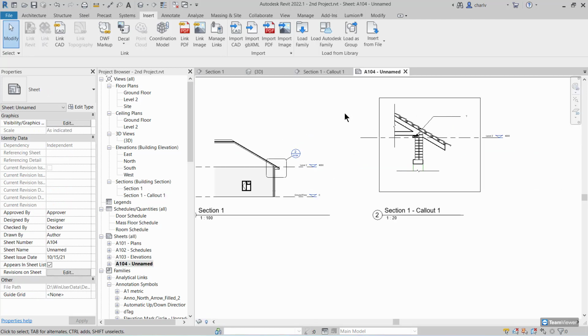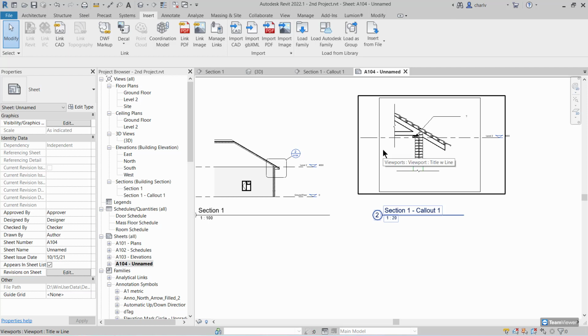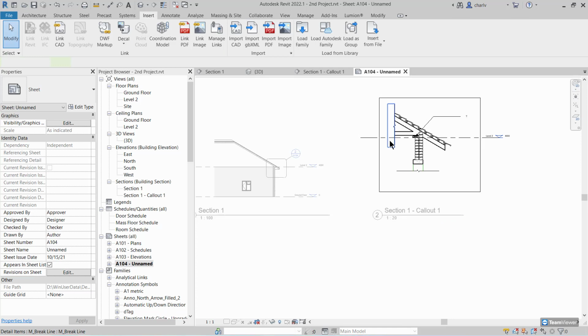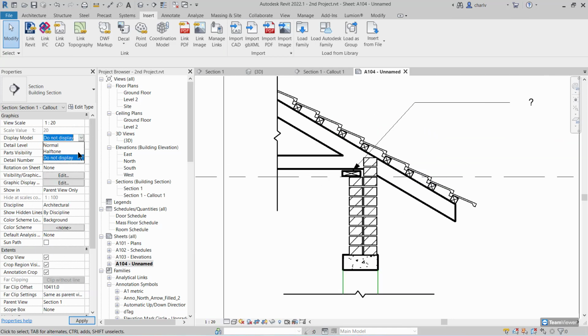Obviously, if you put that on a sheet, it's the same idea as earlier. All right. So that's one way to increase your productivity, is to reuse details. And when you do hybrid modeling, meaning you've got 3D and 2D in the one detail, as I mentioned, go to that detail and just switch off or half-tone the 3D model, trace over it, and then eventually set it to not display the 3D model, revealing your 2D items.